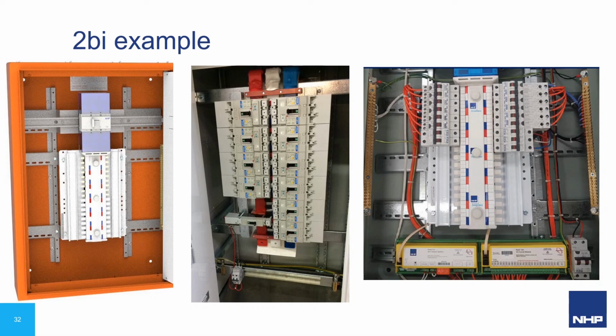Miniature circuit breakers are inherently IP2X in their designs, so there is no requirement for additional covers. If moulded-case circuit breakers are used with larger terminals, then terminal covers will be required on the line side of the breaker to maintain separation from the bus bar.